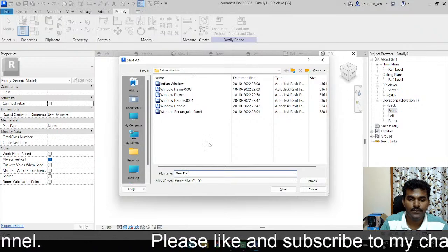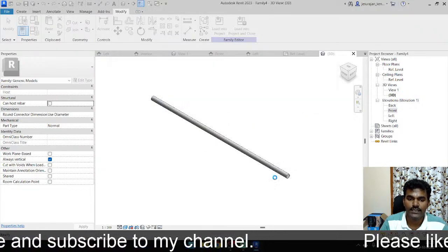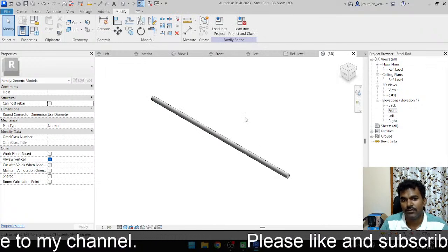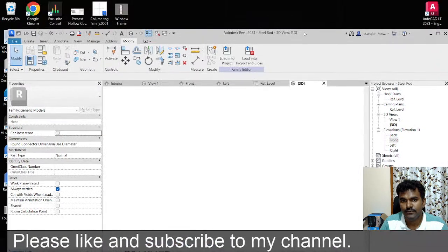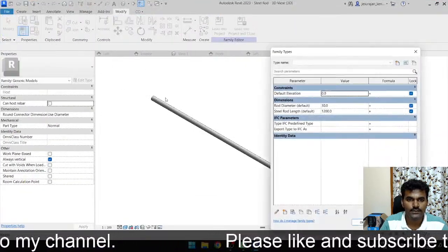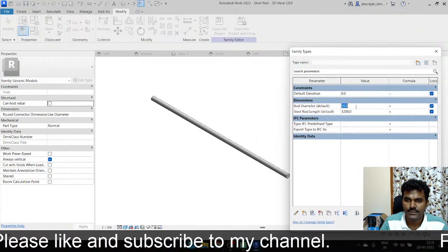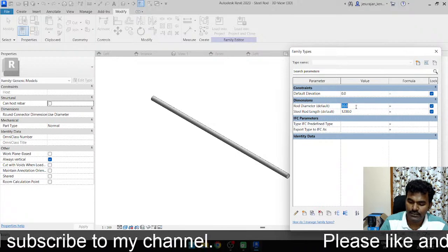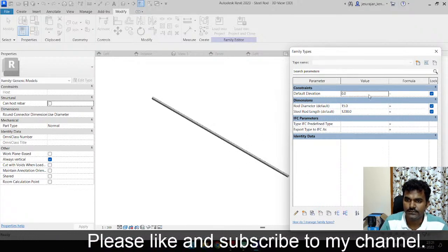Go to options, keep it 1 and save. Oh, now this is saved. Steel rod. Okay, how this will work: go to type family, they are instance, and the diameter, if I change this to 15, if I apply, it's changing.